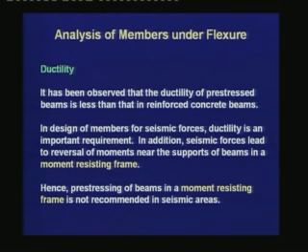We may have prestressed members in a building which are simply supported, but those members are not part of the primary lateral load resisting frame. The primary lateral load resisting frame should have conventional reinforced concrete beams with appropriate detailing to have adequate ductility and to have adequate capacity under reverse moments.